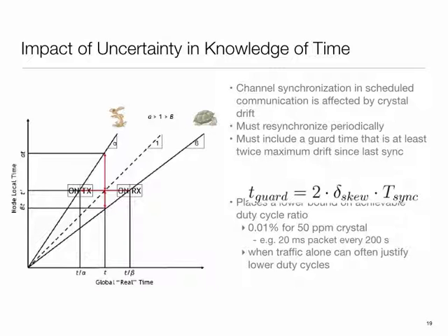So in this particular case, it's basically saying that the amount of guard band depends upon how the clocks are drifting, that's the skew parameter, and how often we are synchronizing. If I synchronize more frequently, the clocks will drift less during that period. And if I have more stable clocks, then the skew is less, then also I'm better off. So there's an interesting nexus out there.